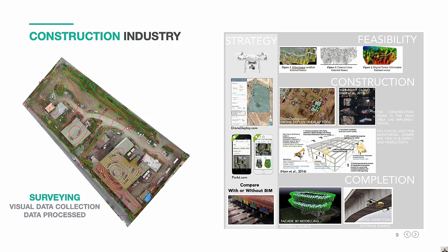For example, if you are willing to build in a very jungle area and you don't know what is down in the jungle until you get there walking, with the drone, when you make some photogrammetry, you can have a surface model that allows you to have access to the surface and identify, for example, if an area is more prone to floods than another area.